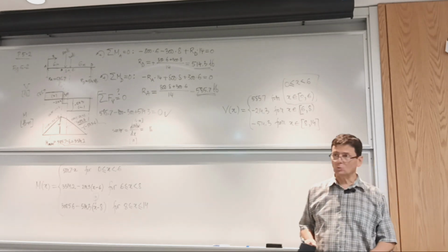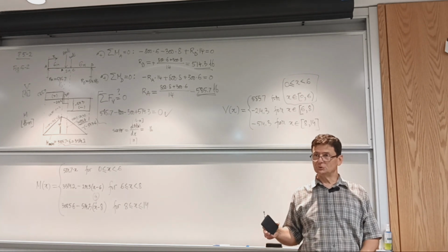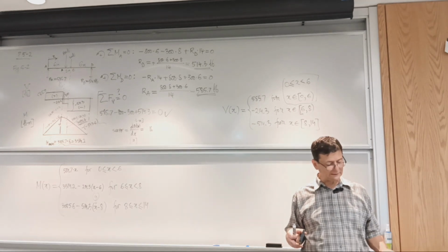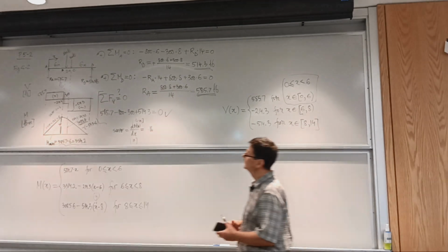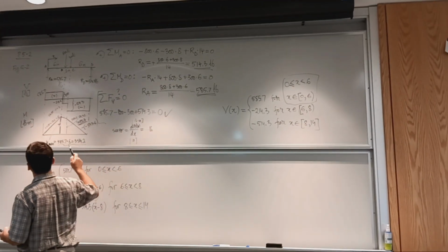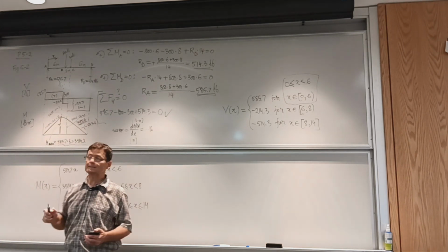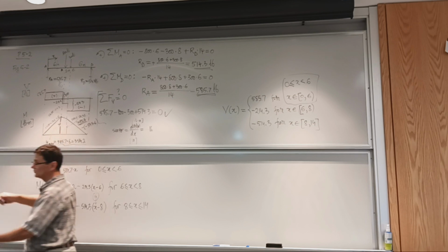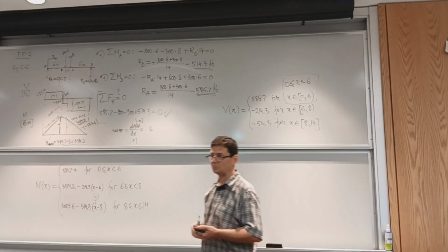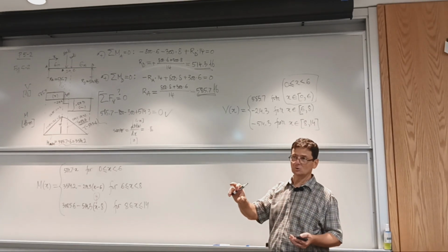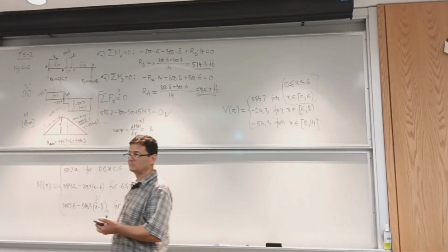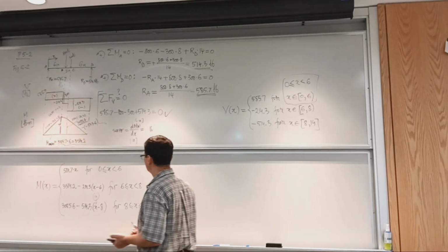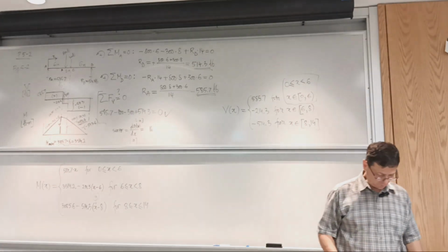I was going quickly over this part because once you refresh your memory about area moments, then we can do actual stress analysis. So after this chapter 7, we take the moment at a location of interest, and we can calculate the minimum and maximum bending stresses based on knowledge of the cross section. And if you're given the type of material for which you know the yield strength, you can calculate the design factor and validate the design. We're going to go over some additional process.